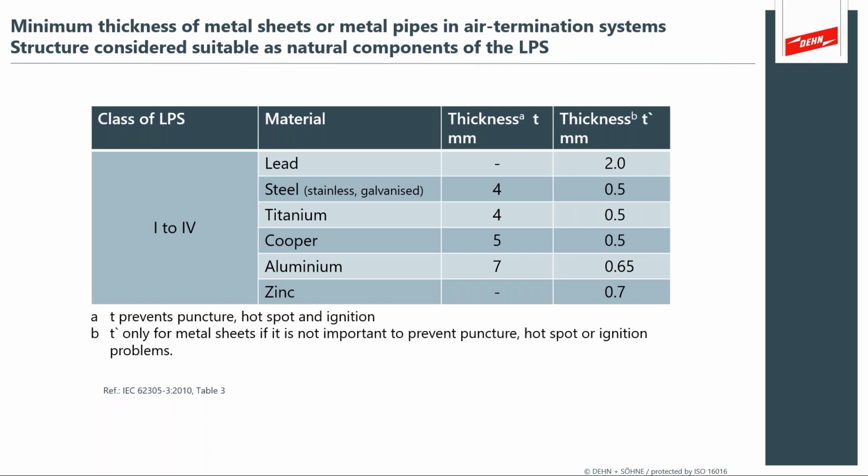There's also indications in the standards that allow something like a big thick metal oil tank to serve as its own natural protection, as long as it's earthed correctly. So the standard allows you to use your discretion and to evaluate the materials of the structures and determine what you can use and what you can't use as natural components to avoid that direct strike and that direct damage.